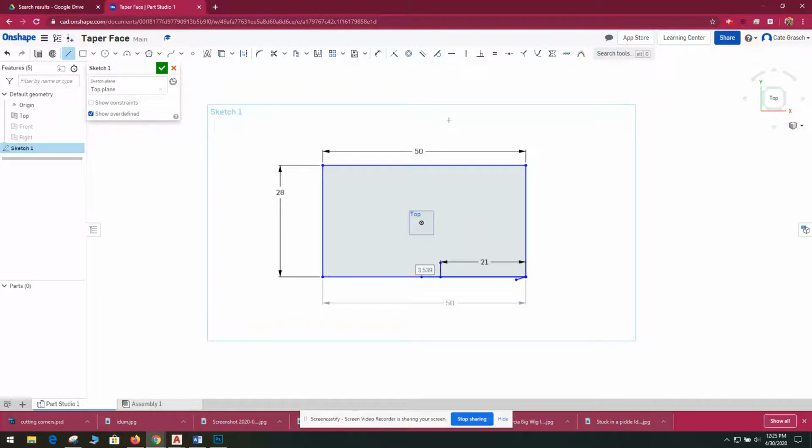And then from this one, draw a line up and then make it 14 because the center is 14. Okay. And that'll put where your center of your circle is. And if you look at your diagram, the circle itself has a radius of 7. It's 7 up and it's 14 up and 14 out. And it's centered on the rectangle, and the rectangle is 28. Okay, so make sure you understand why this is 14. So I'm going to drag this out and then re-measure it to be the diameter of 14 that I want.